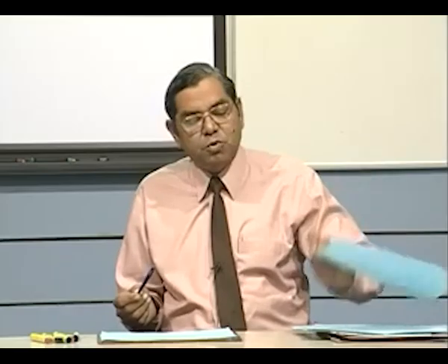So we would like this idle time to be as small as possible. An ideal situation would be when the line is perfectly balanced, that everyone is doing the same amount of tasks. But that is generally not possible. Why? Because the times are integral, number one, and then you have a constraint on precedence. You can't group everything into everything else. You are not weighing, for instance, rice, that you can put something here and make it exactly 250 grams. It's not possible to do that, because you are dealing with these individual entities which have to be grouped together.